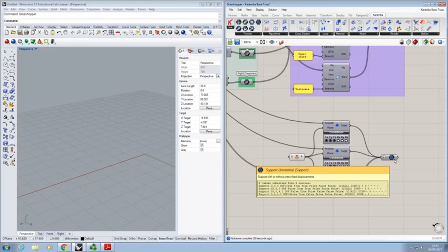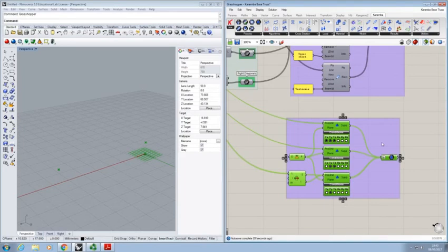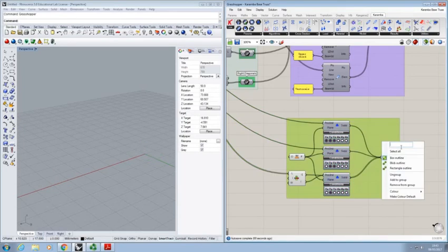So you can see that there's more written that is not actually seen in the component, which is the restraint is for all load cases, and the displacements at those points are constrained to 0. So if you wanted to have a prescribed displacement, then these lines will be altered to whatever displacement you wish to impose. So that's the supports setup complete. We can create the group here again. Call it supports.